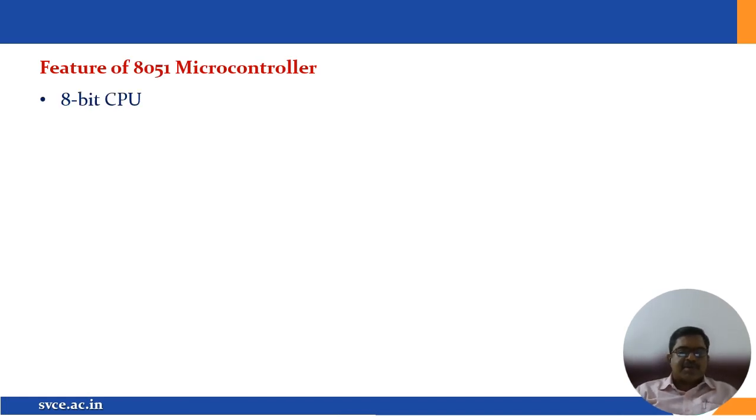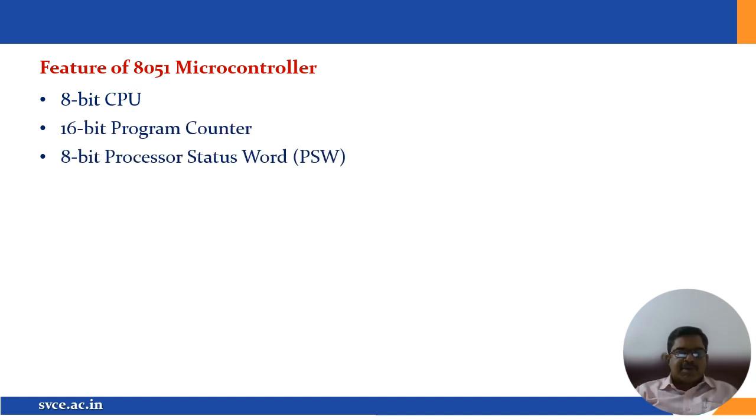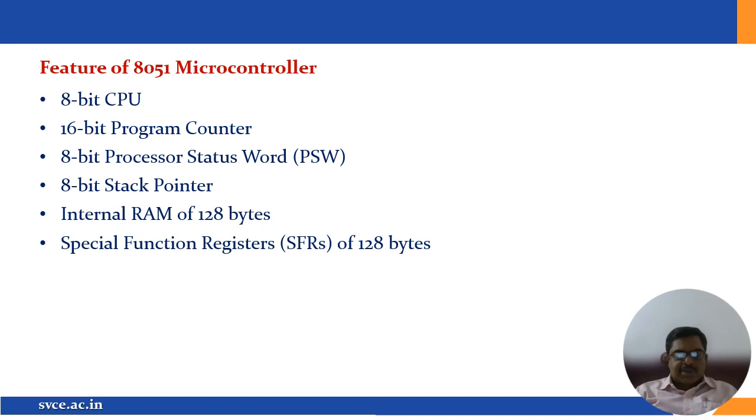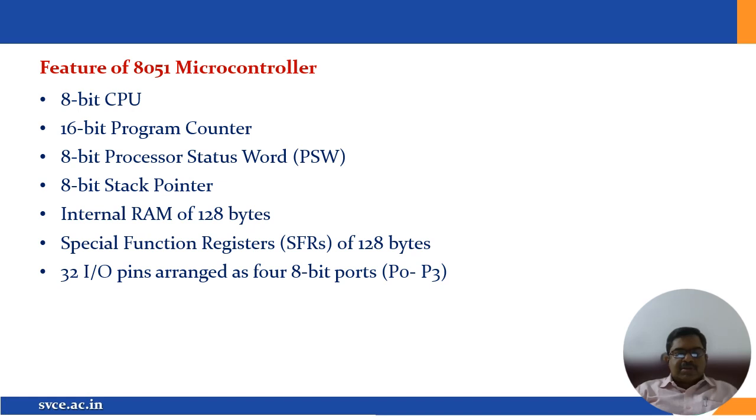Features of 8051 microcontroller: it is an 8-bit CPU, 16-bit program counter, 8-bit processor status word (PSW), 8-bit stack pointer, internal RAM of 128 bytes, special function registers (SFRs) of 128 bytes, 32 I/O pins arranged as four 8-bit ports. So we have four ports.